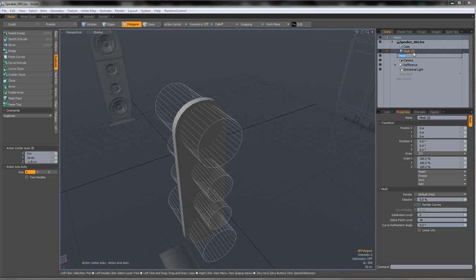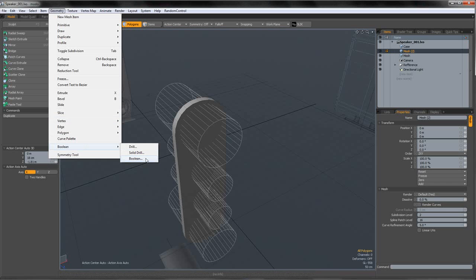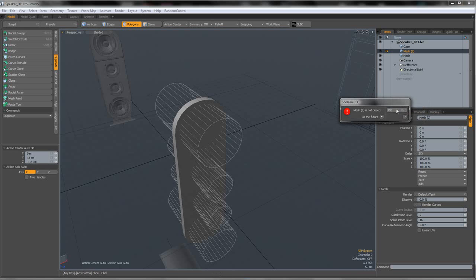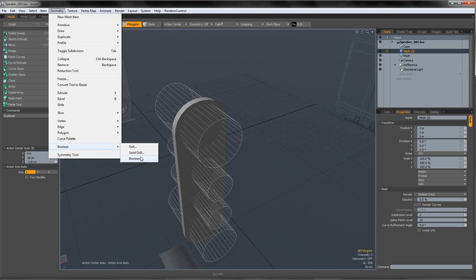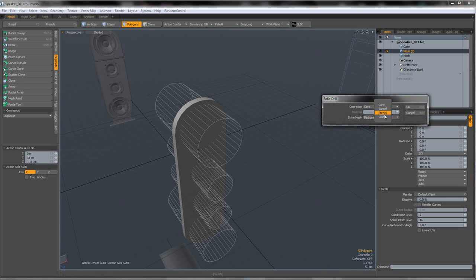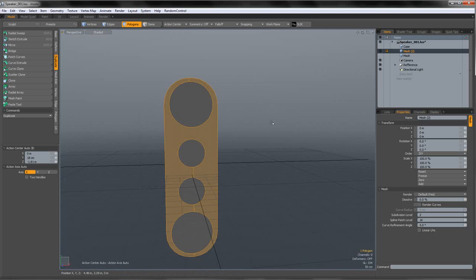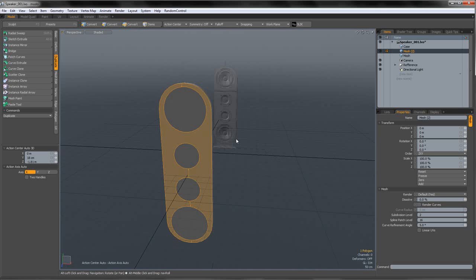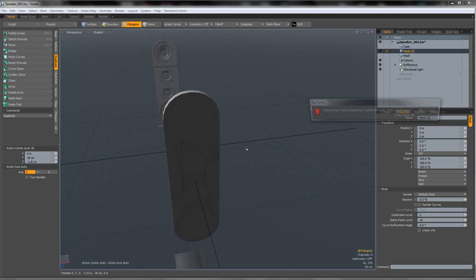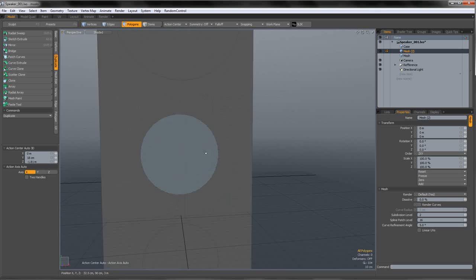And now we're gonna go over to this layer, go to geometry, boolean, subtract background. Oh, I'm sorry, the mesh needs to be closed. So one way we can go around that, if you have a high density mesh and you don't really know where the hole is, go to solid drill stencil, and you're gonna have a hole. Now, regarding this ngon here, you can either triangulate it, or you can leave it as it is. Won't really matter in this case.